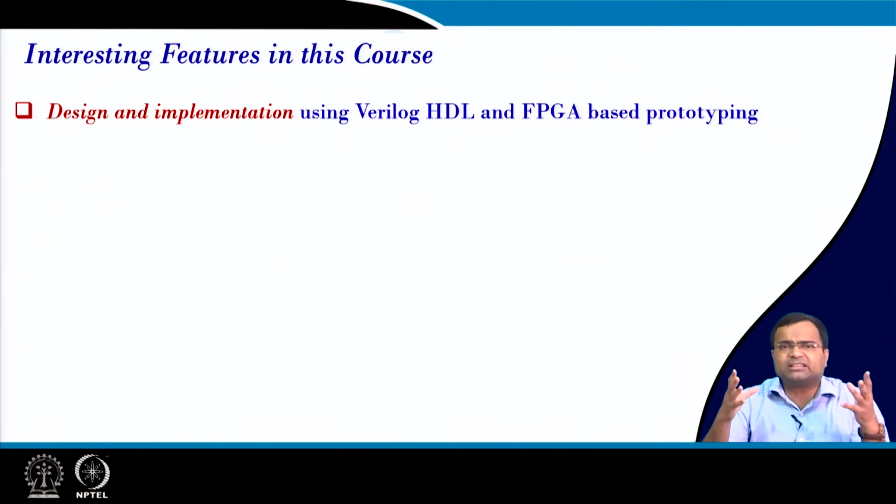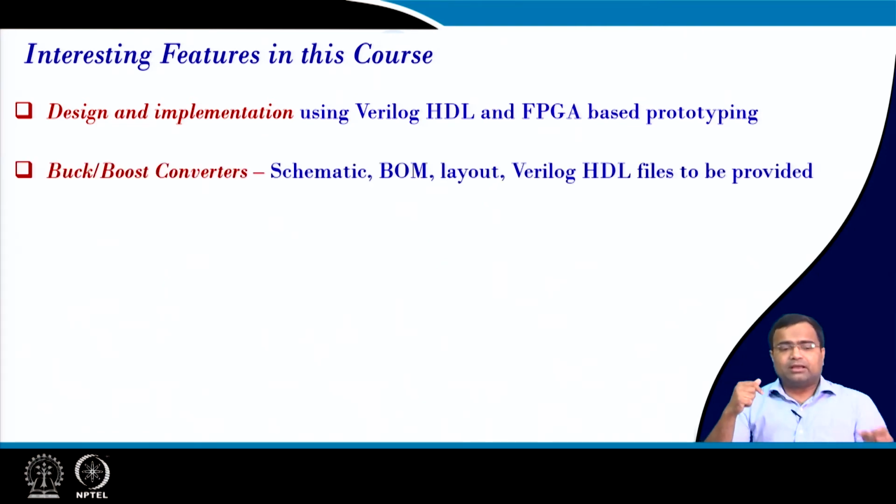We will try to study some aspects, but this will be mostly for demonstration purposes, and may not be part of the exam. We will show Verilog HDL based FPGA prototyping and the steps for implementation, and we will be using a buck and boost converter. I will also show a picture of the test setup in this lecture, and we will provide the schematic of our test kit, that means the buck and boost power stage, and also the schematic and layout file for the signal conditioning board. We are using an off the shelf, commercial Xilinx FPGA kit.